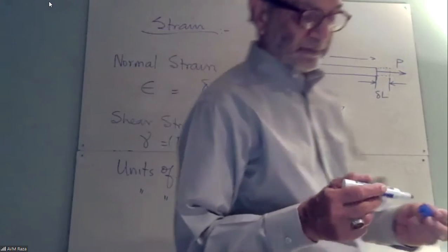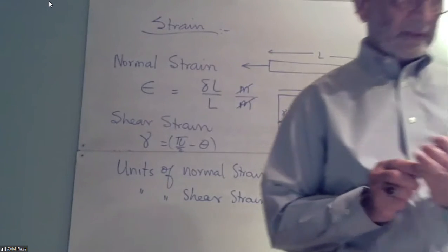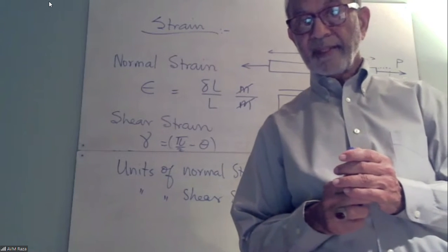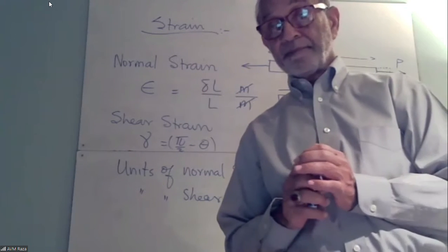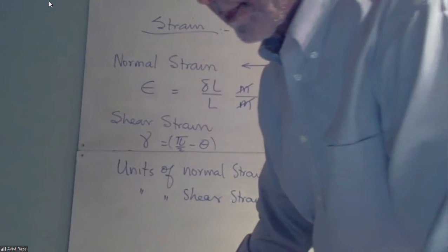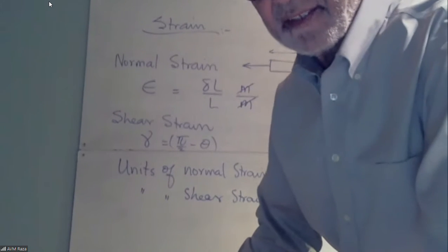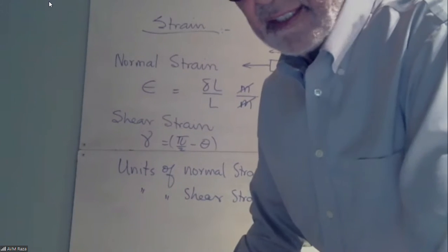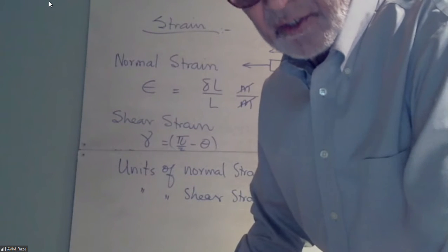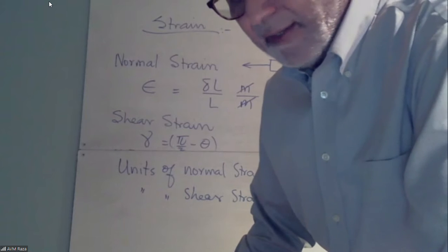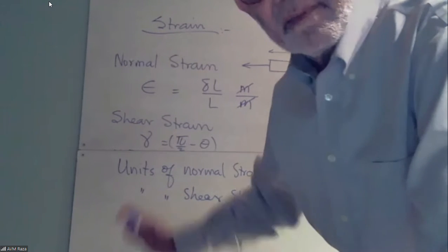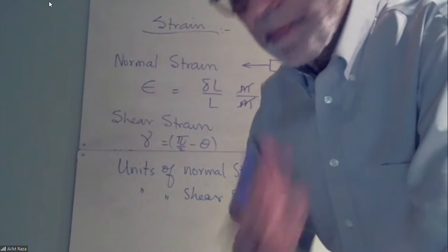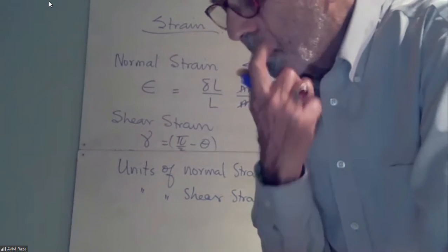For the units for normal strain, did you say inch per inch? Correct. Wouldn't that mean it's without units as well then? Yeah, that's what I'm saying. You got it right, exactly. So it doesn't have any units. It's a unitless quantity. However, by convention, the units are repeated as inch per inch or millimeter per millimeter. It probably just signifies also which system you are in.